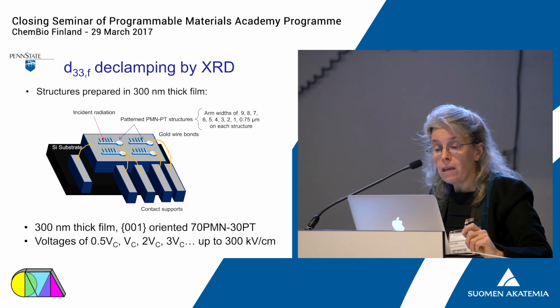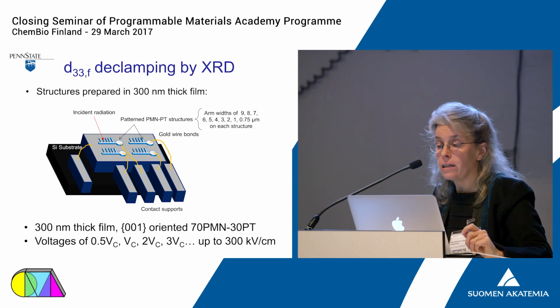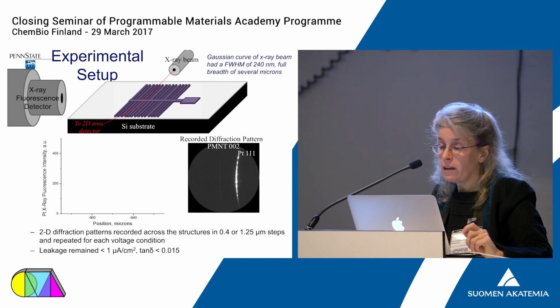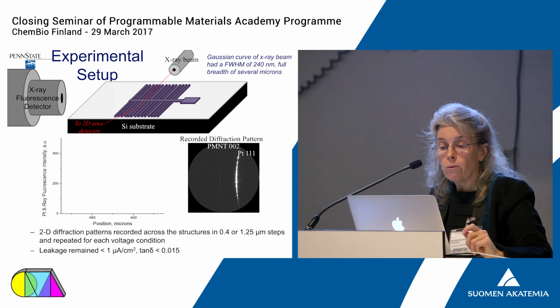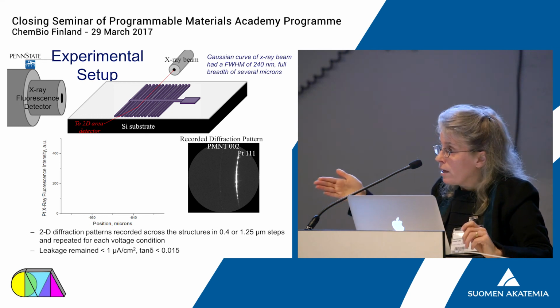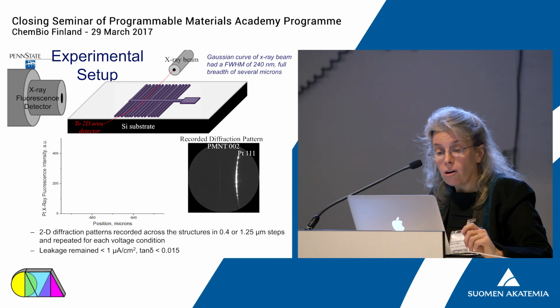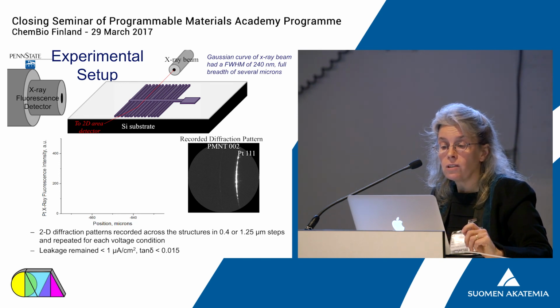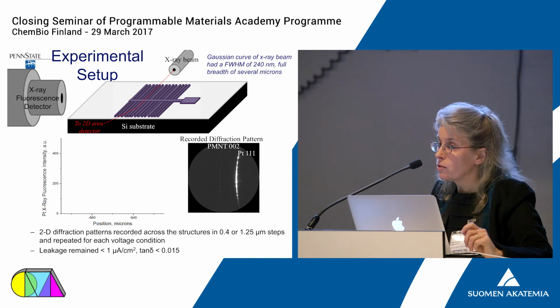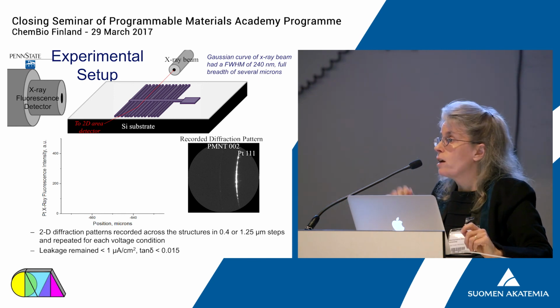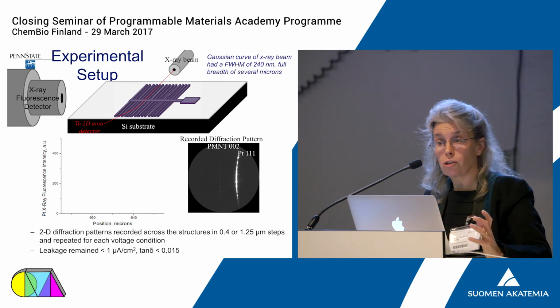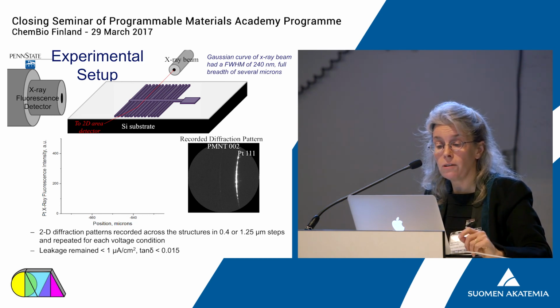To do this, we made strips of various widths by a reactive ion etching process, went to the Advanced Photon Source, where we could use an X-ray fluorescence detector. As we laterally move the piezoelectric element, we can detect where we are on that device via the fluorescence detector, and then we can use an X-ray beam to simultaneously measure the X-ray pattern, and we can do that as a function of voltage. So we can measure the piezoelectric coefficients of these films.